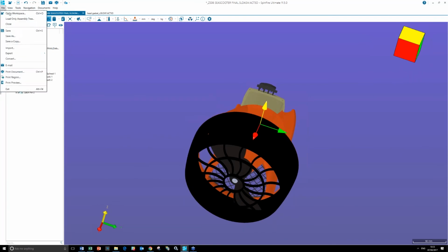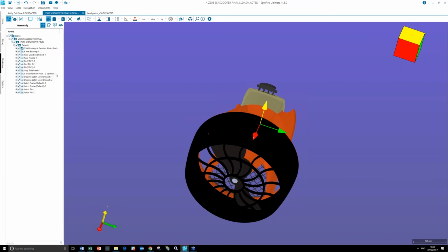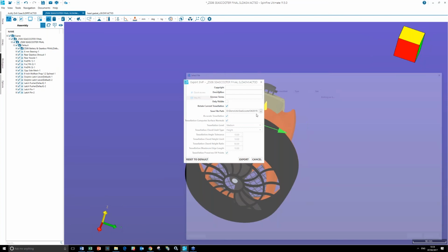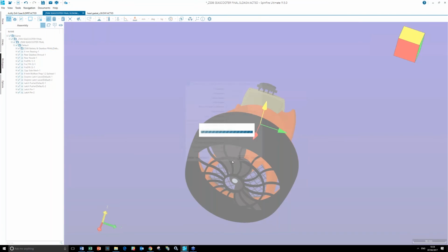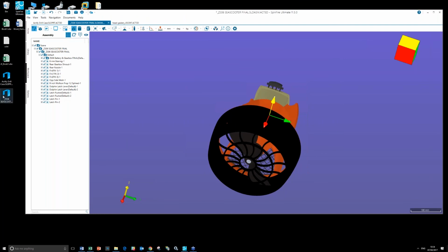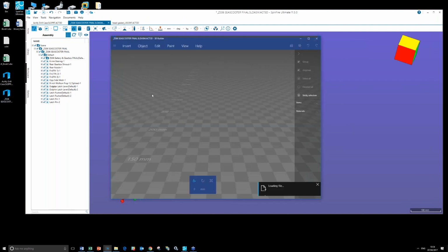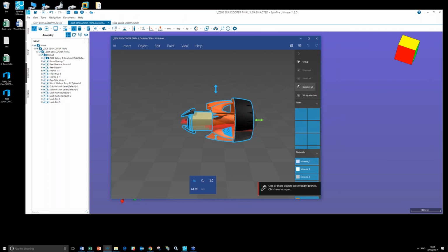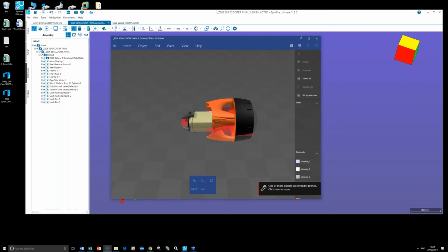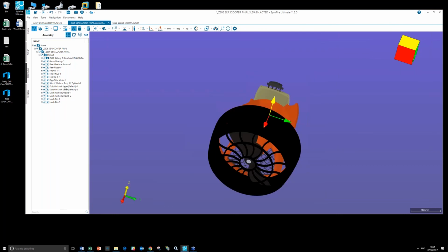And if we go back to my workspace again, and go File, Export, and then 3MF, you can then export this model, and then in Windows 10, for example, I can now open that file in the 3D Builder that comes with Windows 10. So we have the scooter now. Yes, I need to zoom in. And in this scenario, I could then do 3D printing to a printer.